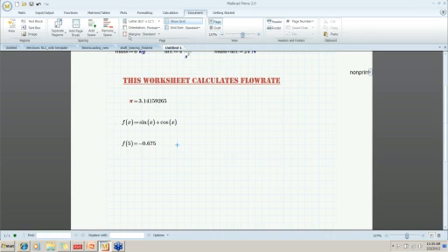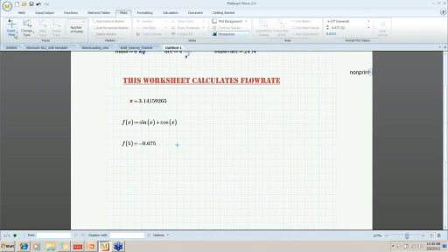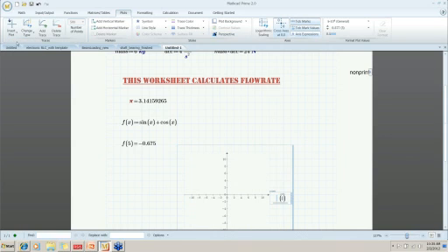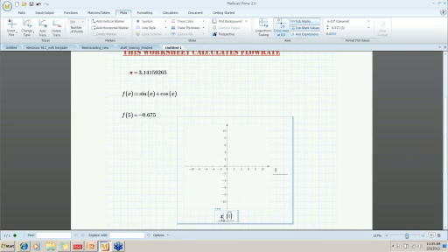We're going to go up to the plotting tab here. Okay, so now we're on the plotting tab. Now we're going to click on Insert Plot. We're going to select XY Plot, and that puts in the framework for the plot for you. Now on the x-axis we put x, because that's the independent variable. On the y-axis, we type f of x, because that's the y data. And then there's our plot.